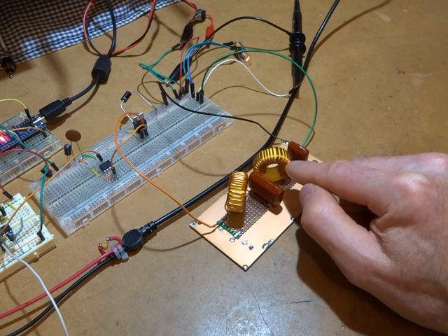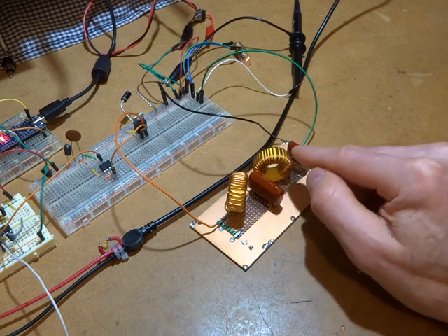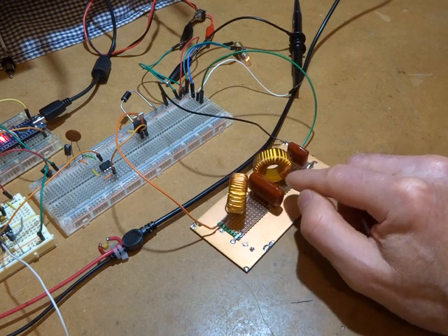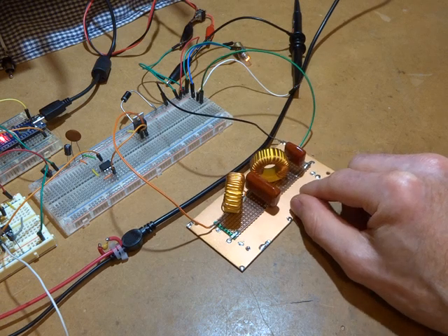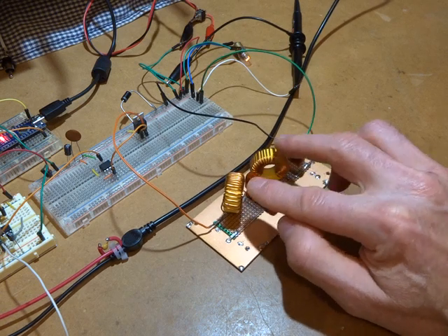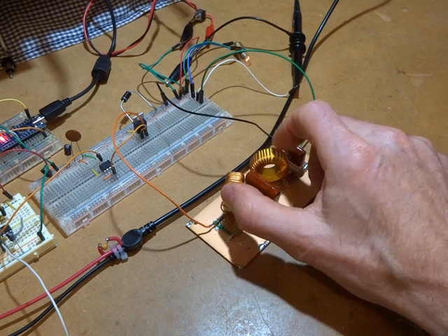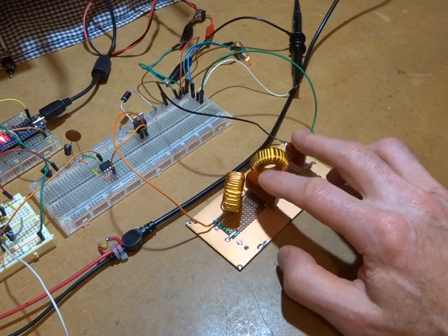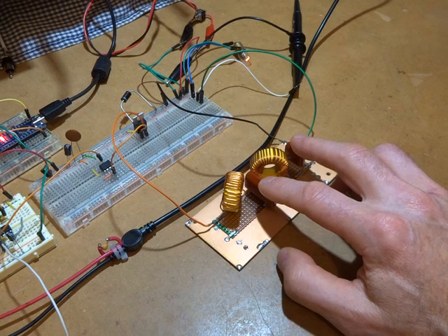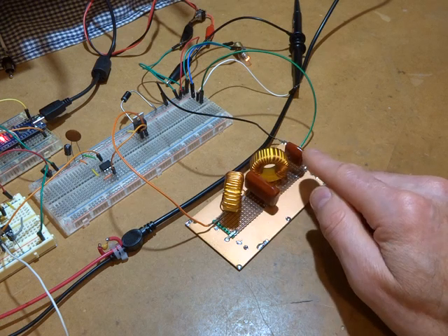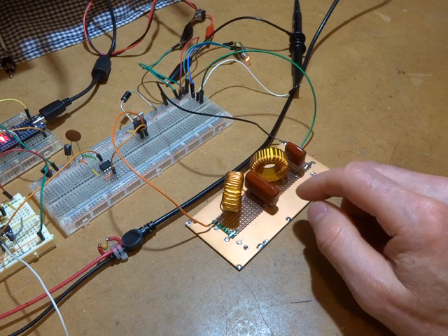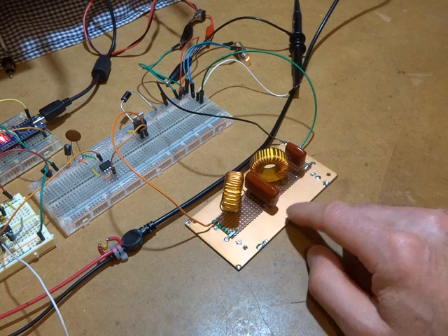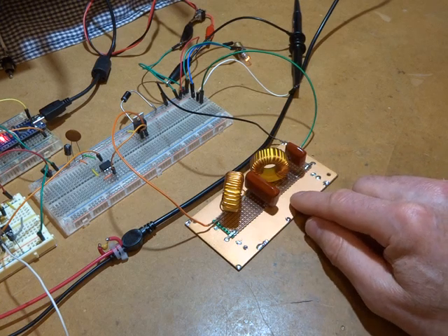So that was quite fortuitous. So it's just a matter of unwinding that and stretching the windings out to get the desired inductance. Those two are sitting at right angles to each other just to reduce the mutual inductance between the two. And like I say, those two high voltage capacitors are, for my circuit, and certainly for the 10 watt transmitter, a bit of an overkill, but I had them available, so it was nice and easy to use.